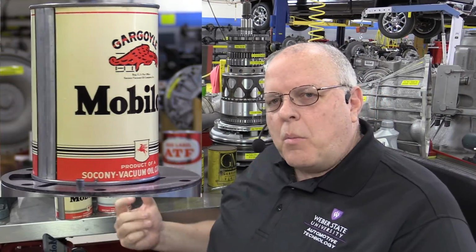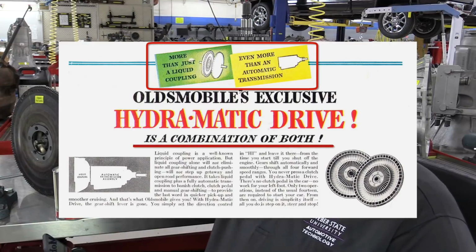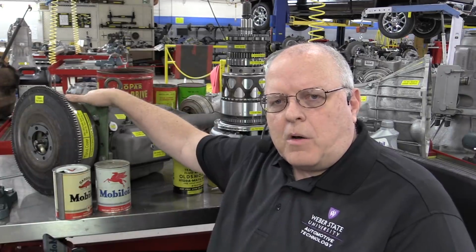So the first automatic shifting transmission from General Motors used motor oil as the lubricant. Well, as it turned out, that wasn't a very good idea. The quality of the motor oils back then wasn't very good, and it led to oxidation, sludge buildup, and varnish coating everything inside the transmission. So by 1939, that same Earl A. Thompson and his group had developed finally a fluid coupling to go with a fully automatic shifting transmission, the 1940 Hydra-Matic transmission, very similar to this 1953 model that I have sitting right here.